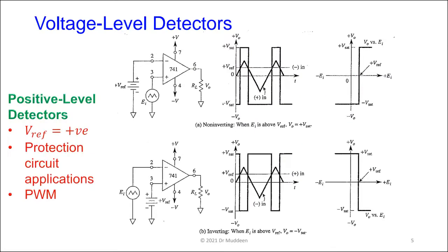Okay. So here's another one now. Here's a positive voltage level detector. So now that we understand how it functions, if instead of putting the inverting or the non-inverting inputs to ground, we put them at some positive voltage, then we get V out of the circuit switching now where it crosses the reference instead. So instead of crossing 0 before, the crossing points are now right here.